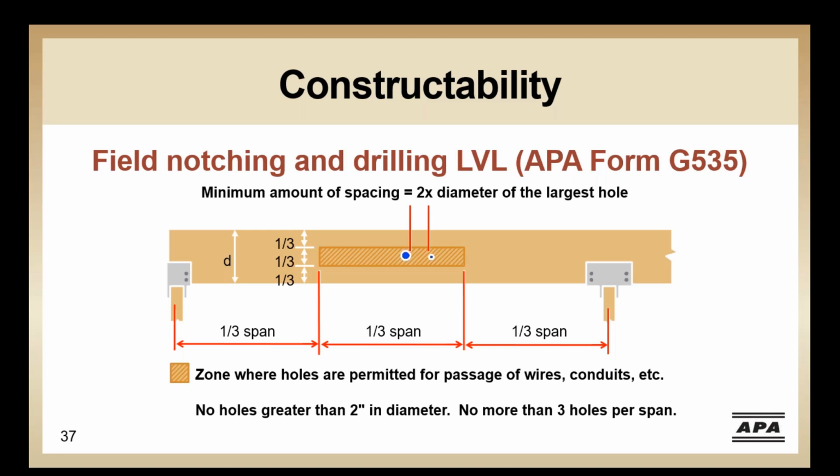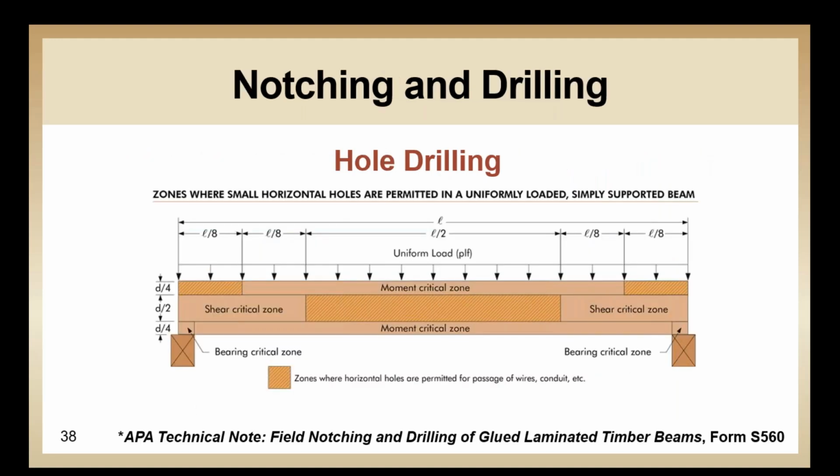For more detail, you can also refer to the manufacturer's instructions, particularly in regard to cutting and notching of PSL and LSL. For horizontal holes in glulam beams, different criteria exist and are detailed in the APA Technical Note, Field Notching and Drilling of Glued Laminated Timber Beams.